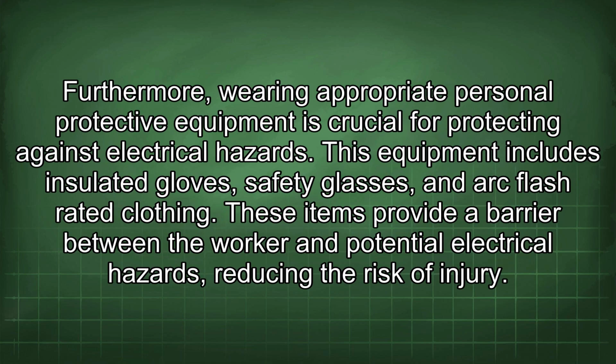Furthermore, wearing appropriate personal protective equipment is crucial for protecting against electrical hazards. This equipment includes insulated gloves, safety glasses, and arc flash-rated clothing. These items provide a barrier between the worker and potential electrical hazards, reducing the risk of injury.